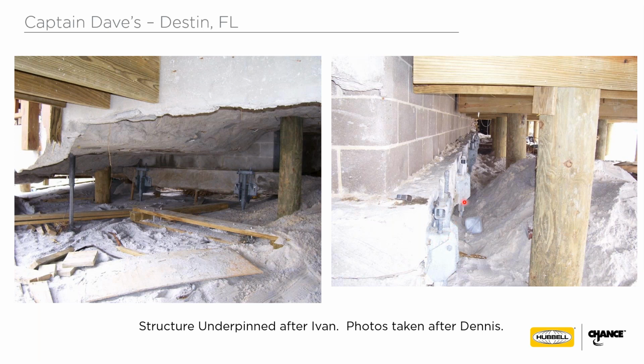Same thing here. This underpinning was done on the beach side after Ivan. And then this new deck was installed that you saw in the previous picture. They pushed sand back in here after the storm, seeing how quickly storms can reappear. But you can see how well the piles supported this wall in the storm event after it was undermined.